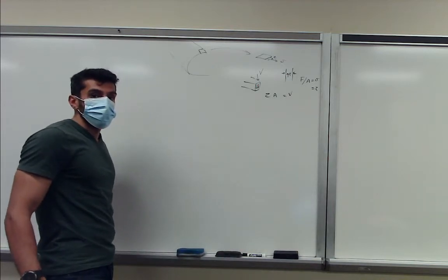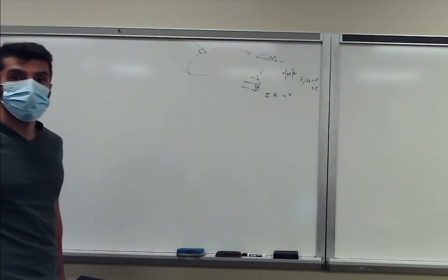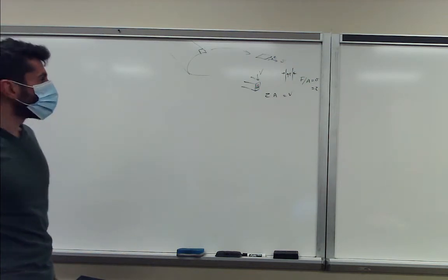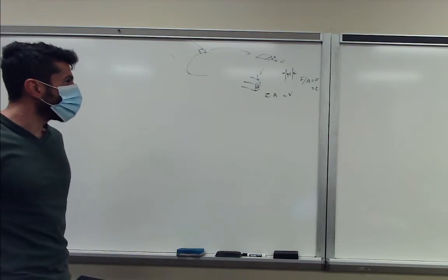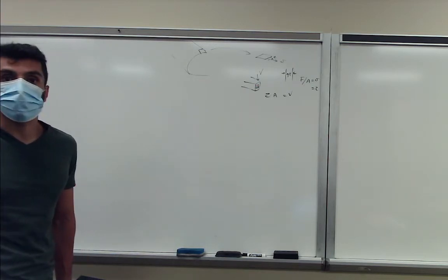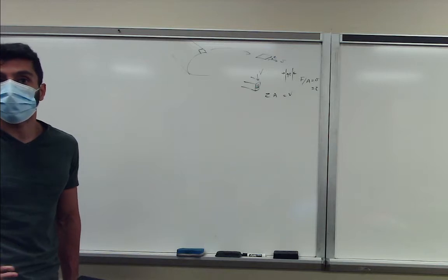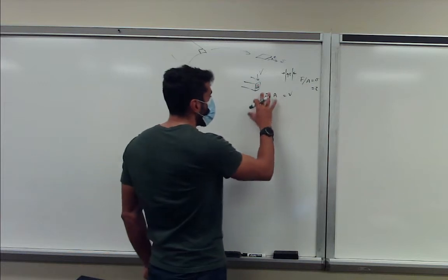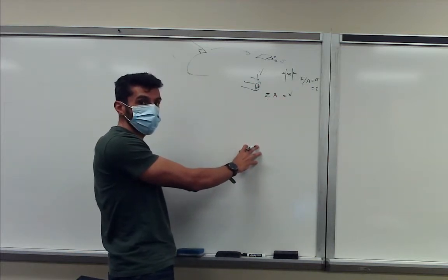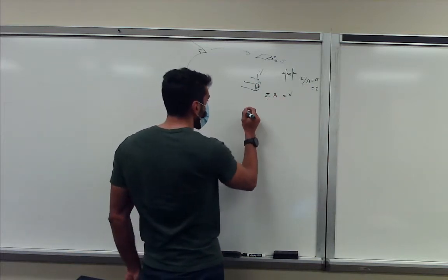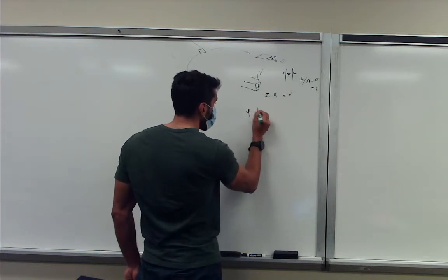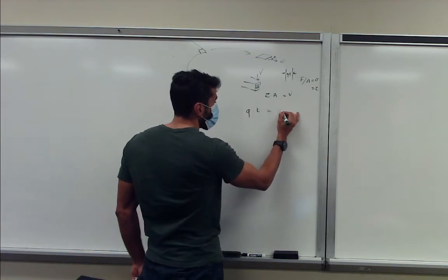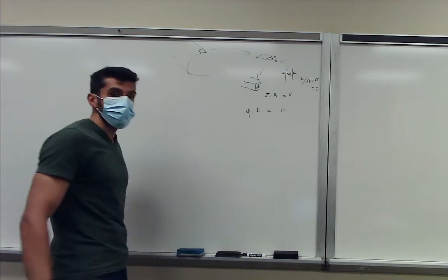So generally speaking, if you're designing something, should we design based on the shear flow or the shear force? You always design based on stresses, because that's the material property that gives you failures. So for the analysis method, instead of going with stresses, we go with shear flows, and then we can still multiply, because once we have a shear flow and we multiply by thickness, then we still get our shear force.